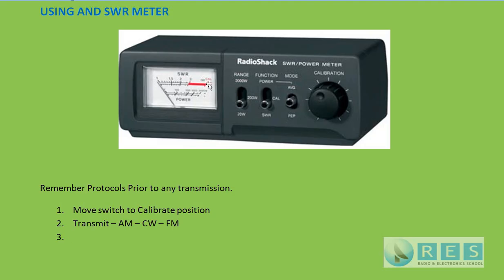See calibrate on the scale there? So we're transmitting. This is on calibrate. When we first transmit, the needle might only come up to here, so we adjust the calibrate knob so that the needle goes all the way across full scale to the calibrate position. There's the CAL on the meter there. So you've done that. The only thing left to do,